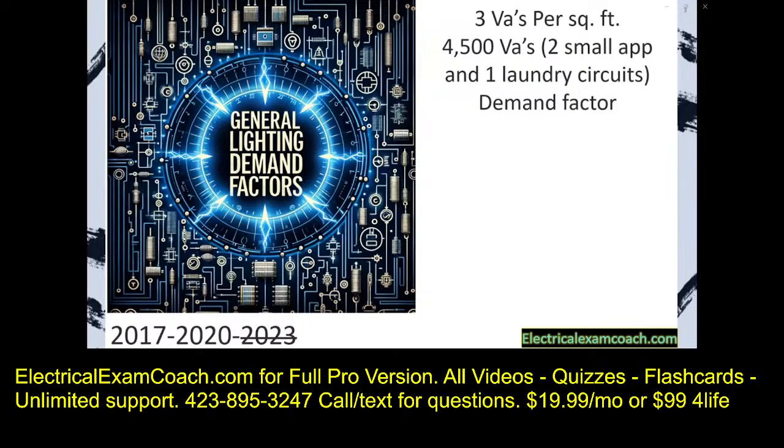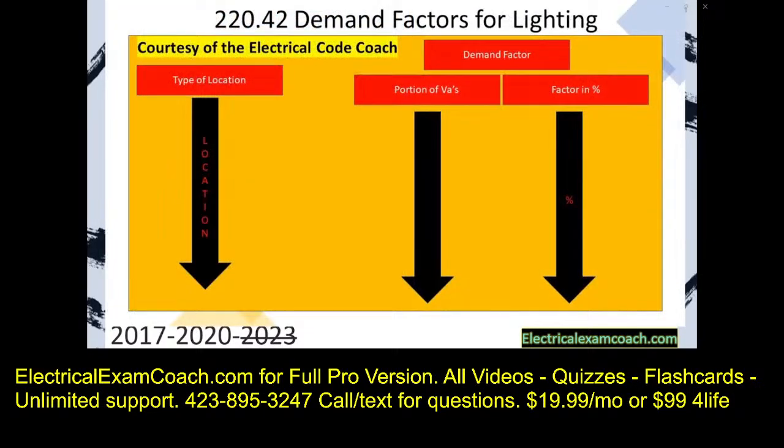But now that we're this far in the program and you are very familiar with using demand factors, I'm going to teach it to you now. And for this one, we're going to head to table 220.42. It's a very important table in our load calculation process. When we get to table 220.42, we always read the black bold heading to make sure that we're in the right table. And it says demand factors for lighting.